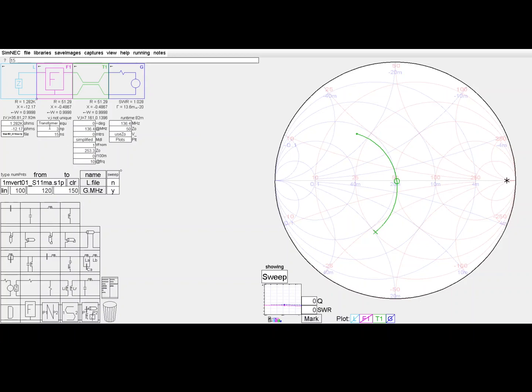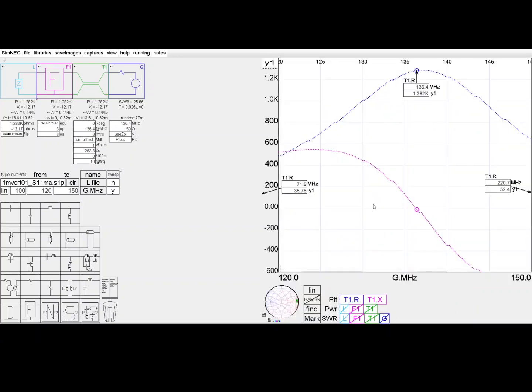And so we'll restore this transformer to 1:1, and there's the signature of a high impedance resonance. If we look at it in R and X terms, there's our peak in R. It's a bit jaggy because there's only a limited number of scan points in the model. But there's your peak in R at the point where X goes through 0.